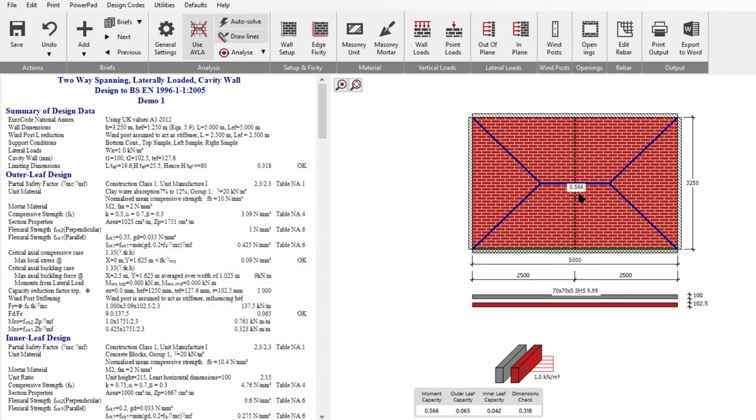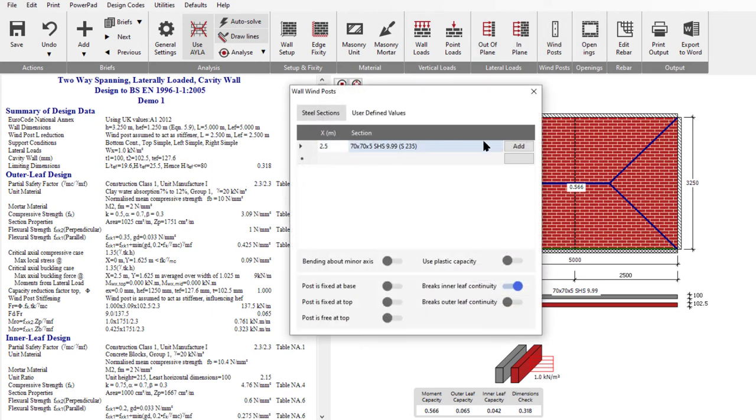And we can see now we've gone from 1 all the way down to 0.5. It's really strengthened it. But what we're seeing here is the U-line pattern, and the U-line pattern is still running straight through the wind post. That means in this area we're still flexing top to bottom. It's going from here spanning to here, which means it's just using the wind post as a strengthening of the overall member. If I go back and change this wind post,